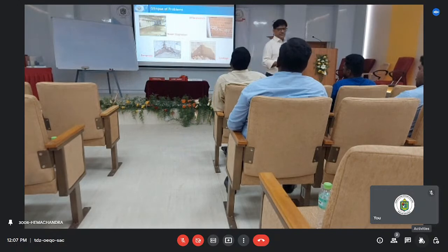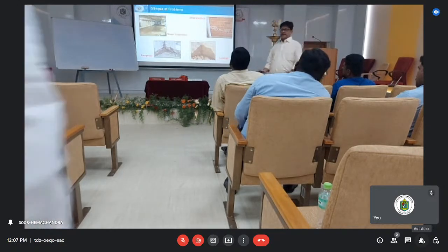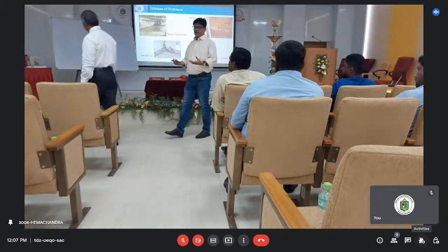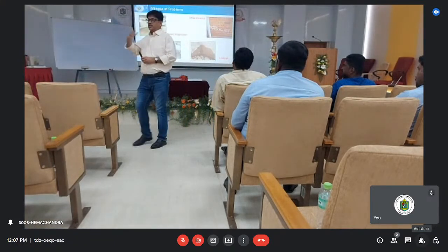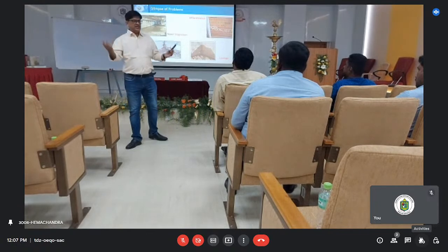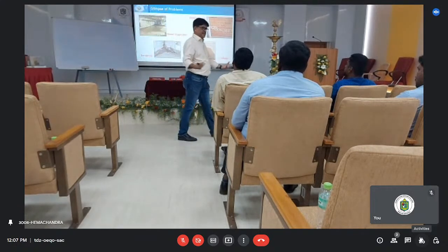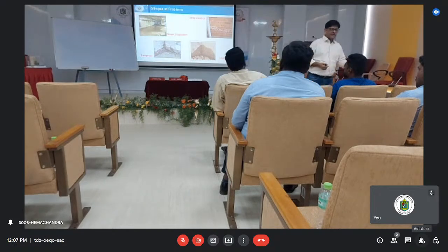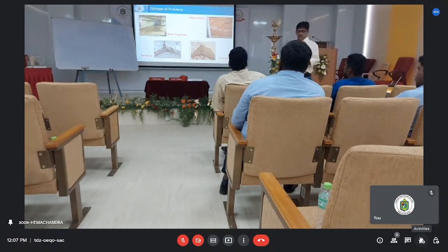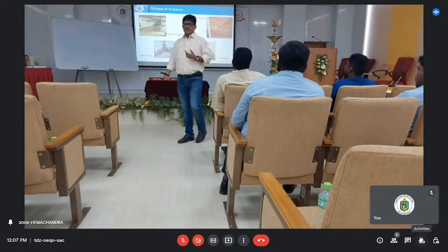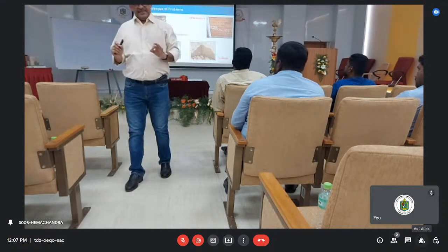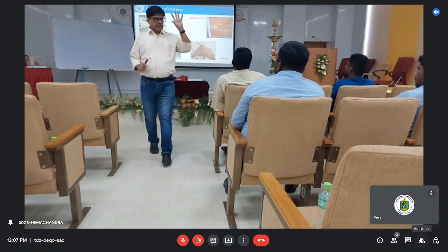We have seen a problem when we have already cast a basement, with or without considering all the water table risk that we discussed, there can be chances that water can penetrate. And as I told you yesterday also, there are three areas from where the water can penetrate. One is from the floor level, one is from the wall floor joints, third is through the construction joints.